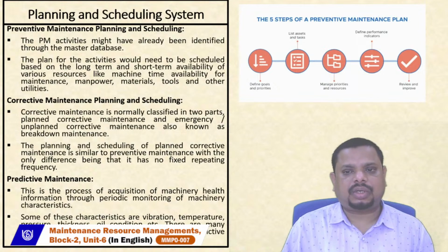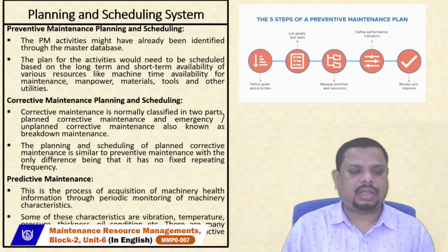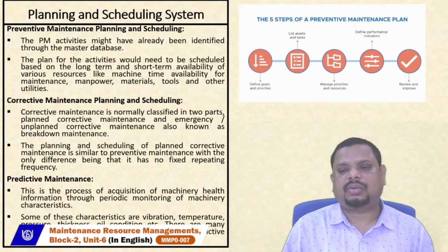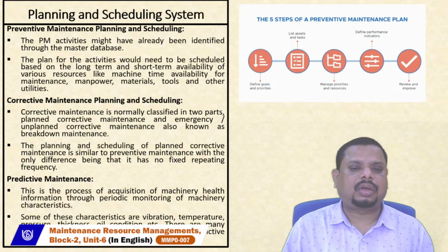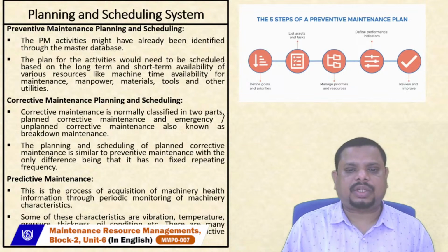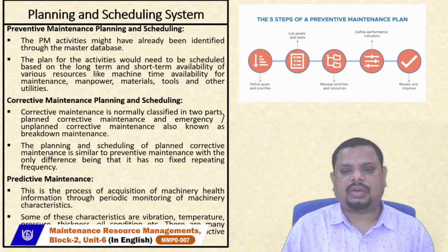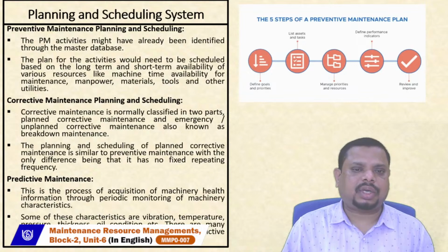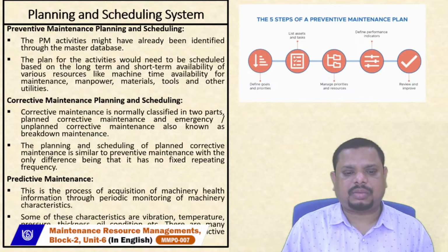And whenever you use condition-based monitoring, they basically provide a large scale of data in case of monitoring of machines and their characteristics. So that before the machines, the gearbox, the engines wear and tear, they'll directly provide the information to the server, to the data cloud, and from the data cloud, the company personnel, especially maintenance personnel, will go for diagnosis of the machines. If possible, they immediately replace the machines so that there is no interruption to the production department.